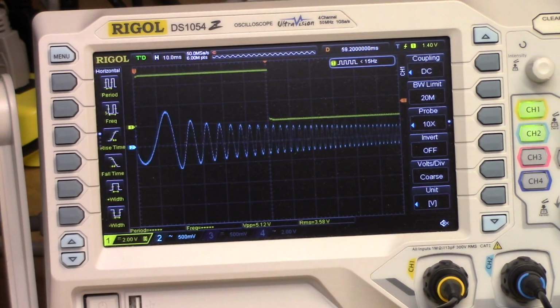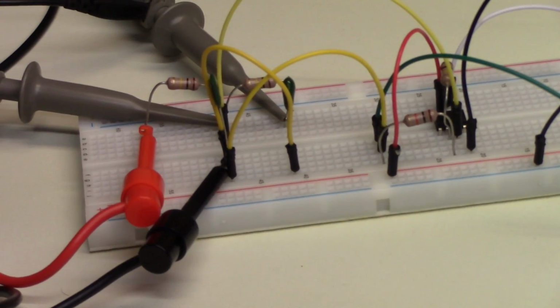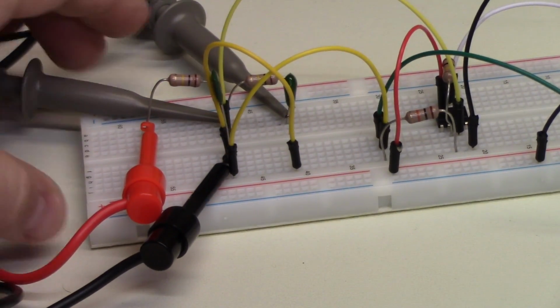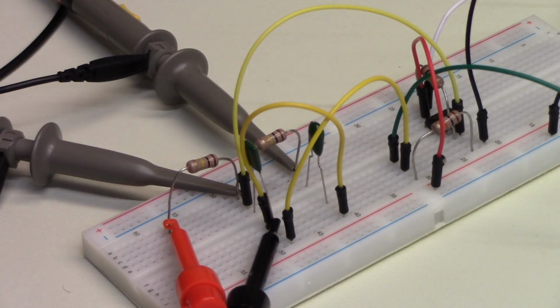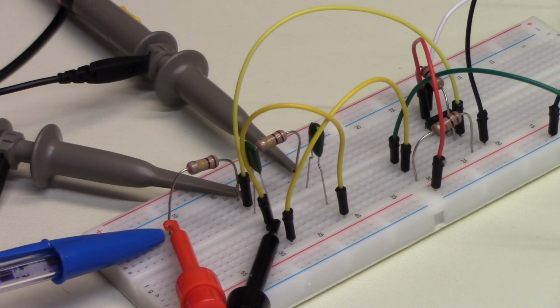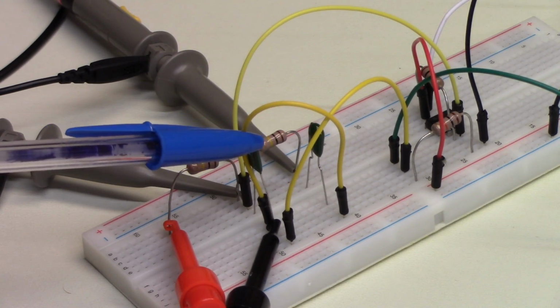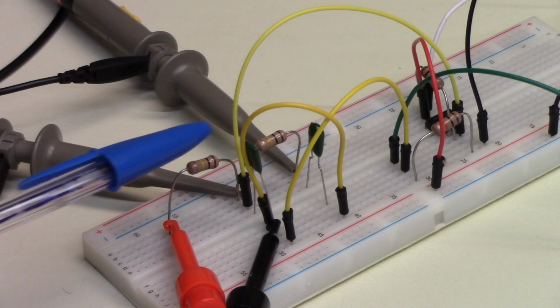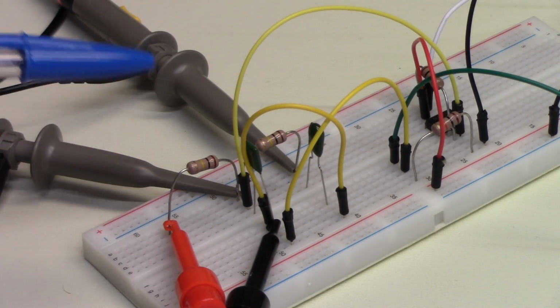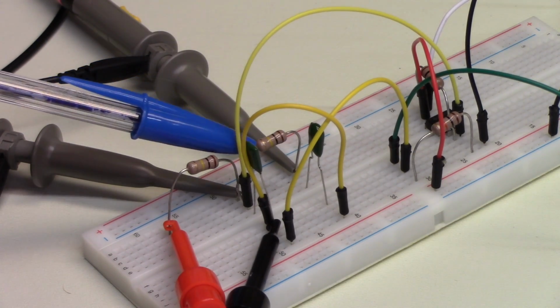You can, of course, string these circuits together, and if you do that, let's just go down and look at how I've done this on the breadboard. So here is my circuit. I've got my signal in, signal out, resistor, and here is capacitor. So this is one complete circuit. But of course I can cascade these things. I can put that into another RC circuit.